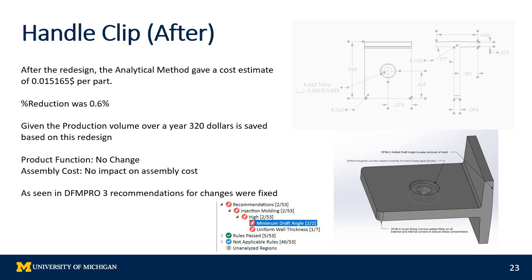Specifically, if we see here, the draft angle to ease the removal of the mold, the integrated locator to add a chamfer to match the lower gear locator, and avoiding the sharp corners and added fillets on all external and internal corners to reduce stress concentration.